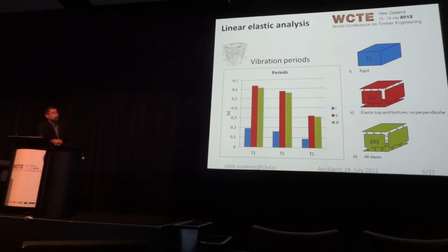The second is what actually should be done, so we take into account the influence of connections, and the third is just an upgrade of the second model. So we also take into account the connections between the perpendicular or the adjacent walls. Now in our case, that's only in 4 places, only in the corners of the structure, so maybe the small difference between models 2 and 3 is not very characteristic of the average cross-link building, however.